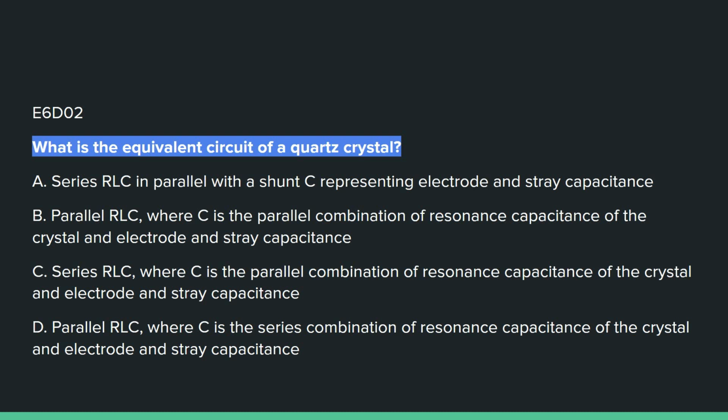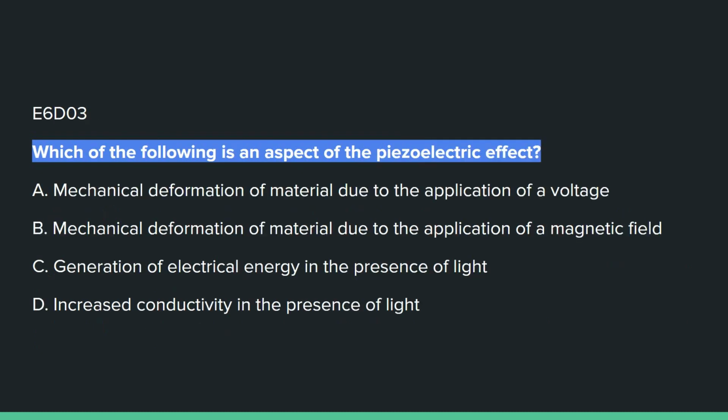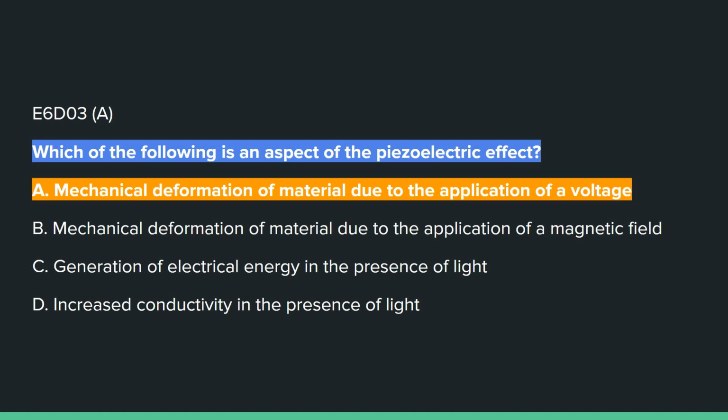E6D02, what is the equivalent circuit of a quartz crystal? A, series RLC in parallel with a shunt C representing electrode and stray capacitance. E6D03, which of the following is an aspect of a piezoelectric effect? A, mechanical deformation of materials due to the application of a voltage.